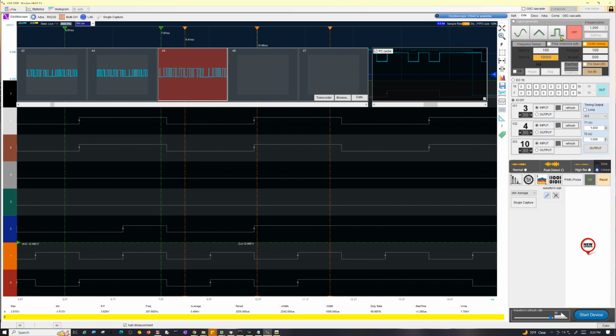And again, this function generator will generate a square wave up to 1 megahertz, a triangle wave up to 8 megahertz and a sine wave up to 13. But even approaching 1 megahertz, this really is a crummy looking sine wave. It certainly isn't a 50% duty cycle, I'll tell you that. But at any rate, you can manually sweep this thing, and you can set it to sweep repeatedly by hitting the cyclic button here, and then you can use the filter, which you should use if you're using that Bode plotter I showed you earlier in Chinese.